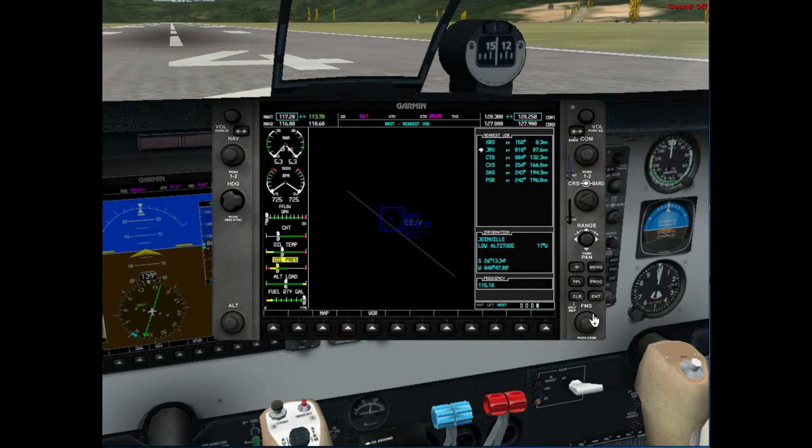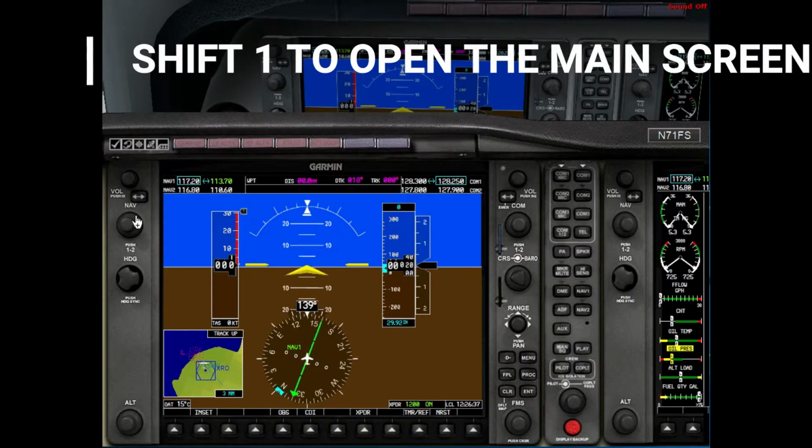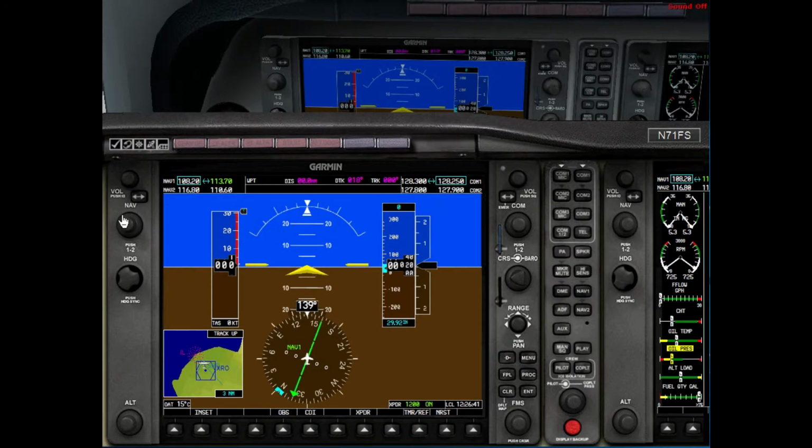You can go to this VOR, and then you have the frequency here. Then you have another VOR, you have the frequency here. Let's take the first one, which is located at the airport where we currently are. This one in Florianopolis is 117.80. You can set the frequency here, 117, and also we use the outer knob and inner knob, 80.